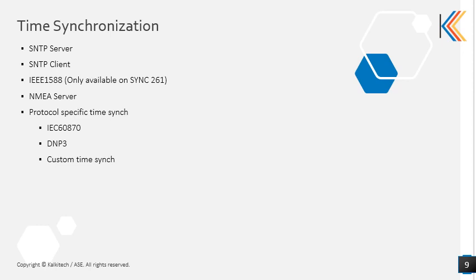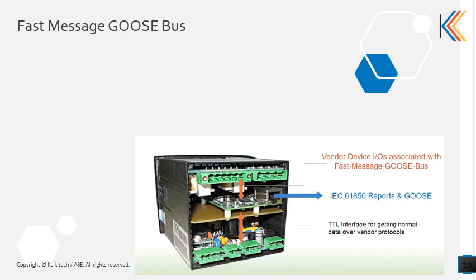If you have a Modbus master internally, the Modbus protocol does not support time synchronization, but we have a custom methodology to support it: we receive time from SNTP and then sync your device over Modbus. That is also supported. So this is a key method.